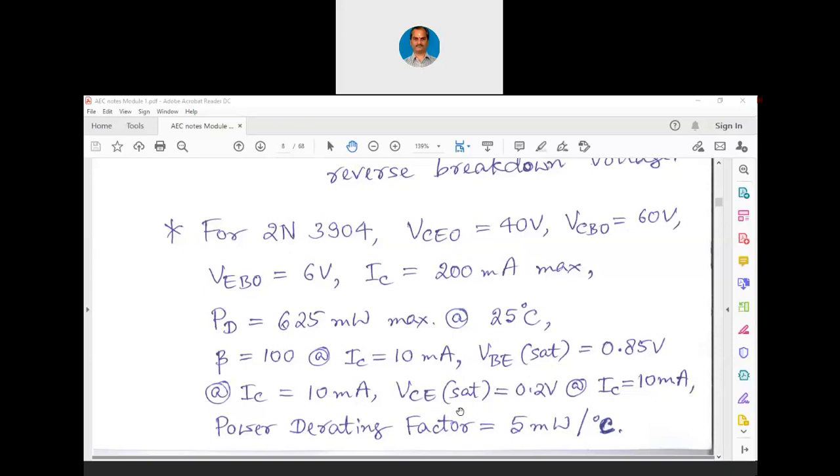Ideally, when the transistor is completely switched on, between collector and emitter there should not be any resistance, and there should not be a voltage drop across the transistor. That is what we expect. But practically, the transistor is nothing but NPN, with P being very small, and we can visualize a single N region there. Whenever the transistor is completely switched on, between collector and emitter we can visualize a single N region, ignoring the base region, because the base region is very small.